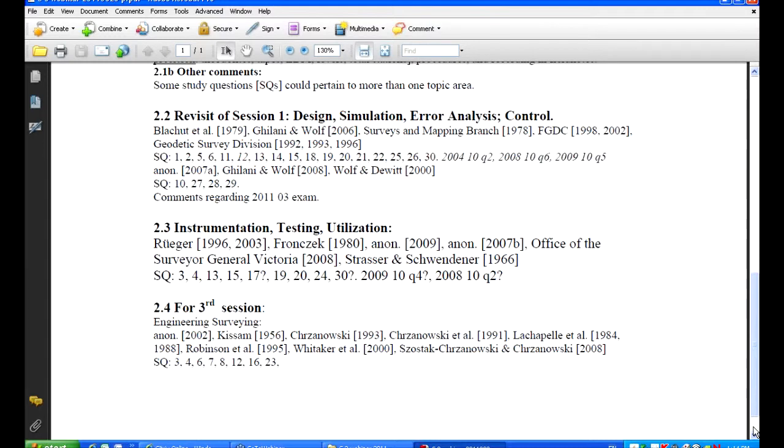So that's the prism offset, and similarly there could be an offset between the electronic center and the manual centering portion of the EDM. So we have a combination of EDM and prism offsets, which are normally referred to as the additive constant, to take the EDM distance and make it into an actual mark-to-mark distance between the two centerings.